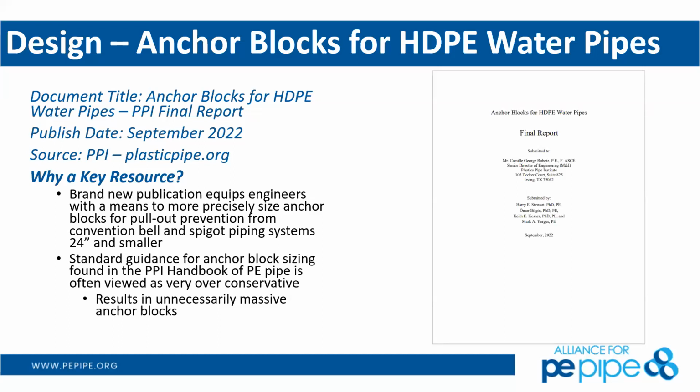So high density polyethylene, if it was just high density polyethylene from A to B, it's called a monolithic system, which means everything from A to B is fused. And so now it's fully restrained as we see any flow movement or temperature fluctuation within that time period. The soil that surrounds that pipe is going to restrain it from moving.